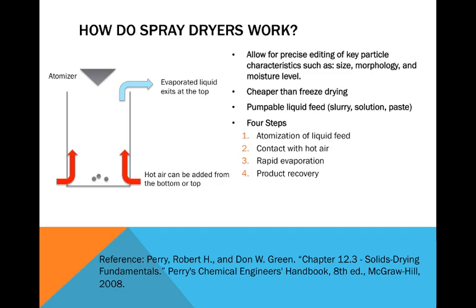In industrial spray dryers, atomization is usually accomplished using rotary atomizers or hydraulic pressure nozzles. Hot air can be added to the system in countercurrent, co-current, or mixed flow. According to Perry's Chemical Engineer's Handbook, co-current is the best option for heat-sensitive particles. During evaporation, the solids in the droplets are kept cool as the moisture evaporates. The droplets may shrink, expand, fracture, or agglomerate during this stage. In most industrial systems, a cyclone may be used to collect the particles continuously.